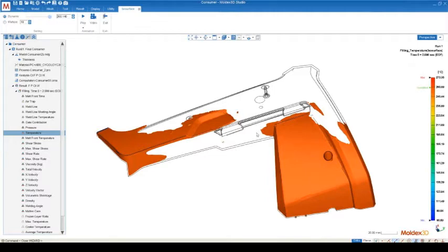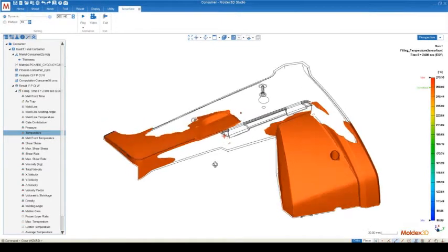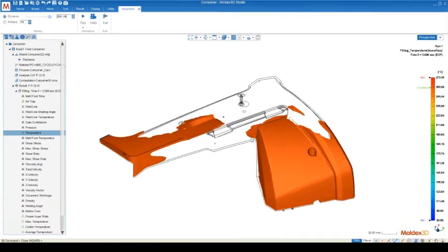I'm just going to end up with a smaller part than what we originally molded. So that's one of the most important effects that I can tell you: look at the temperature and evaluate which effect is dominating. Are we looking at a cooling effect dominating, or is the shear effect dominating because we're filling too quickly? Now, unfortunately, the filling stage takes up probably the smallest part of the cycle time pie. So any optimizations you can make here are great, but you can usually optimize a little bit better in the other stages of your cycle.